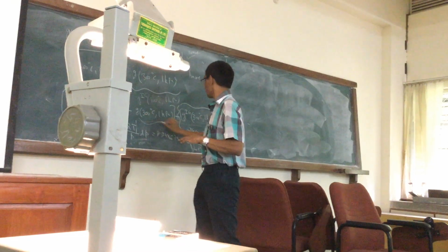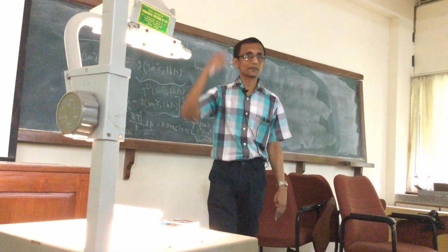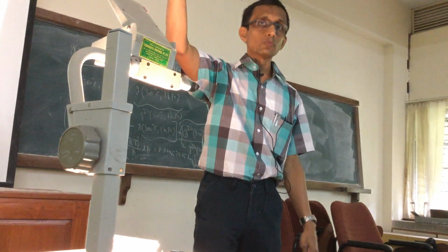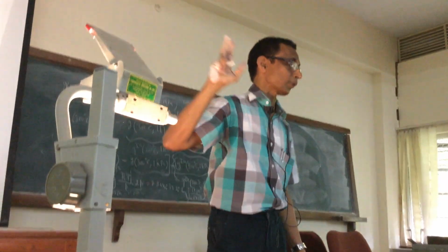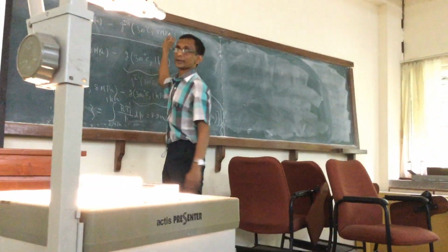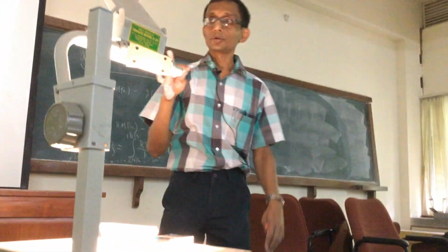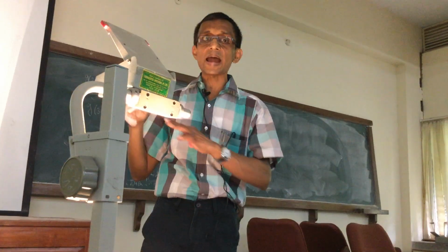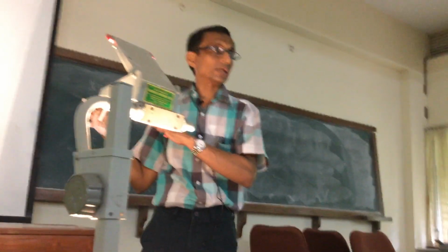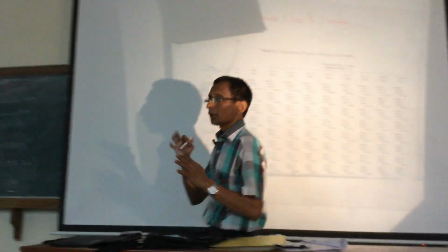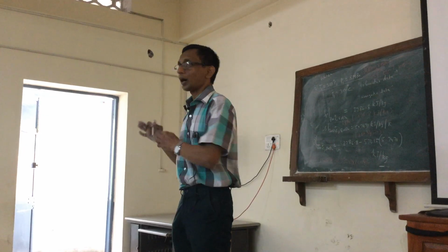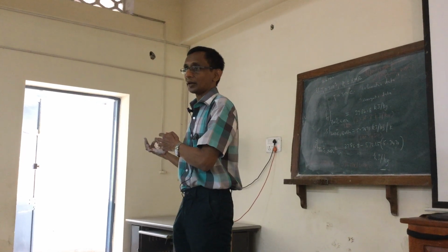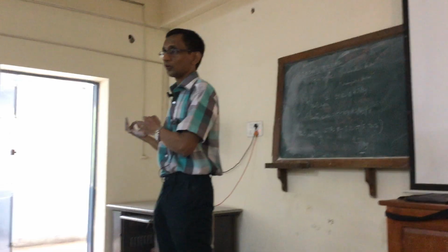Of course, the crucial point I am making here is the value I have got at 1 kilopascal. Why is that also important, as you can see? Even though that doesn't correspond to 300 degrees centigrade, 8 megapascal, it's very crucial to complete the problem. So I'm adding and subtracting two terms which are almost equal to each other. So I'm now expressing effectively the difference that I want in terms of two differences, one which I can directly calculate from the tables and one other which I just calculate using an integral, using a property of the ideal